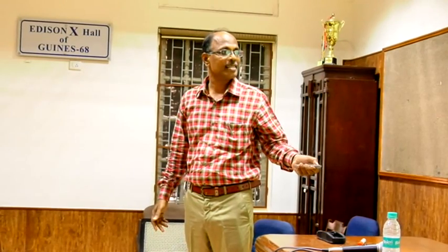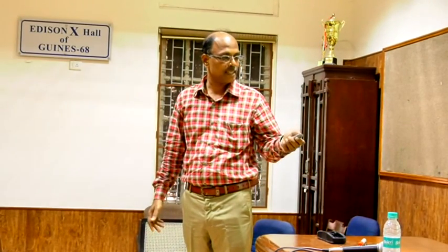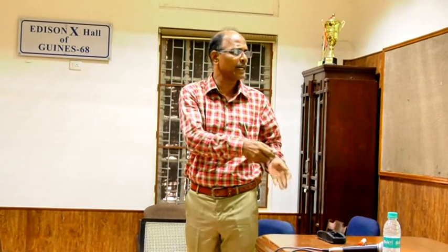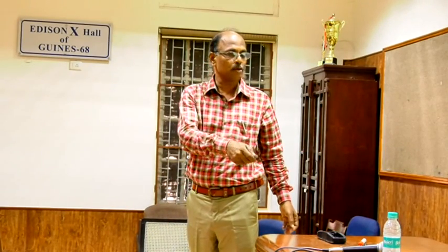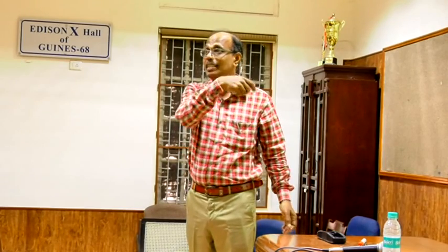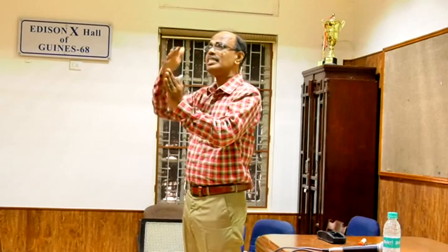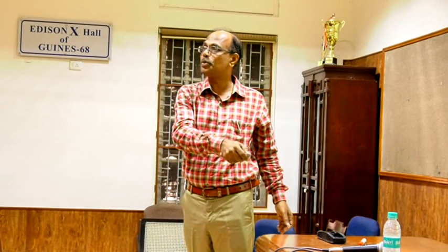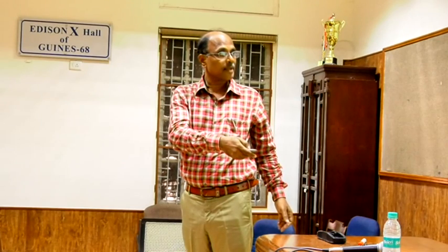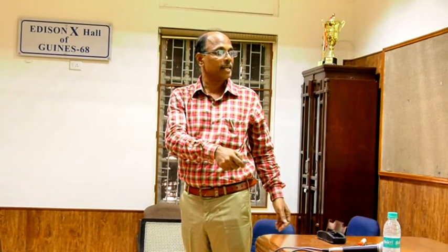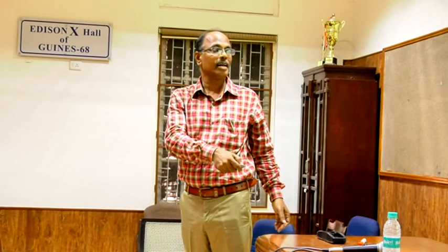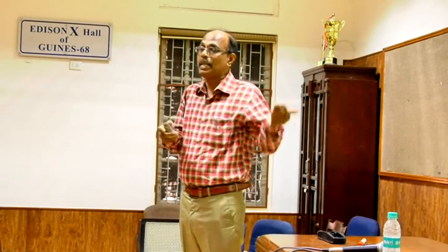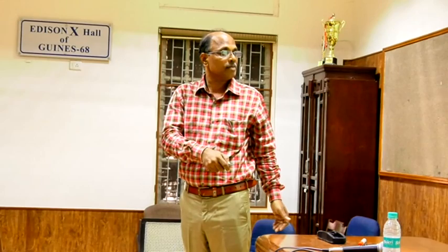Then form the Jacobian matrix. What does the Jacobian matrix mean? The previous problem, this is the Jacobian matrix. If it is not convergent, form this Jacobian matrix. Then solve that equation. How do you solve? Jacobian inverse into the right hand side vector will give the correction values. Once this is formed, find the inverse. This inverse with delta P and delta Q will give the correction vector. Solve this equation. You will get delta delta and delta V, then update delta and V. Update means the previous value and the correction value are added. You will get the new solution. Then go to step 3.